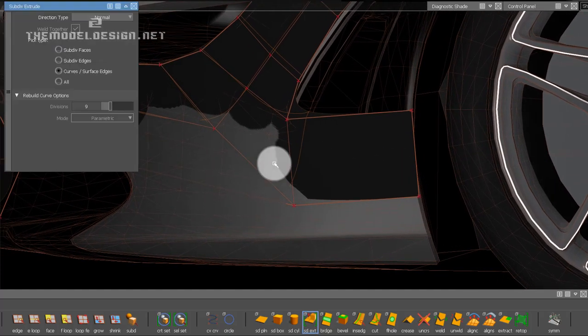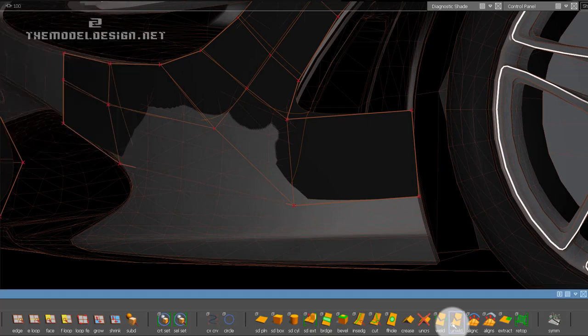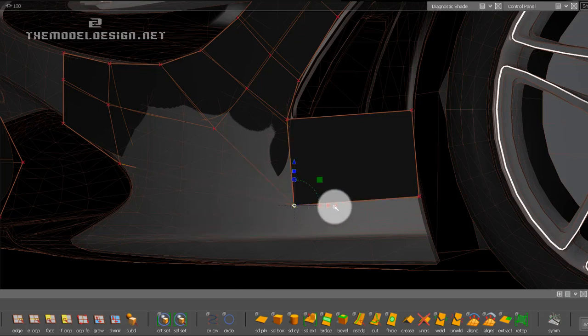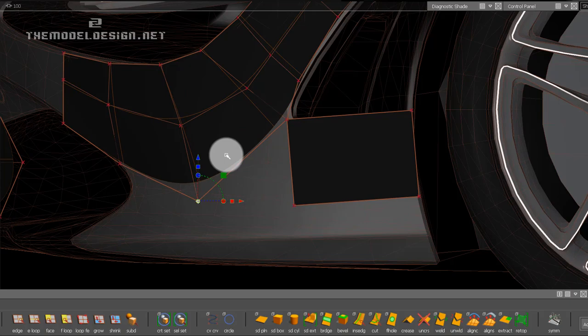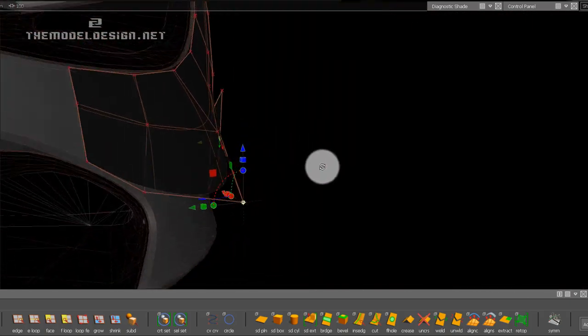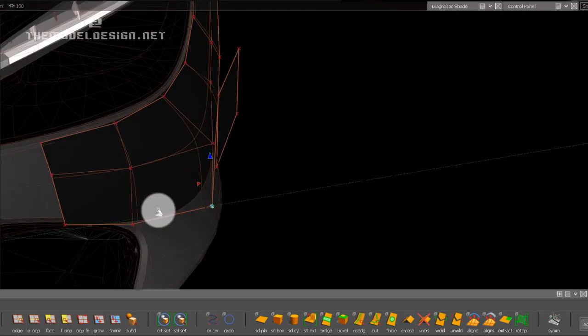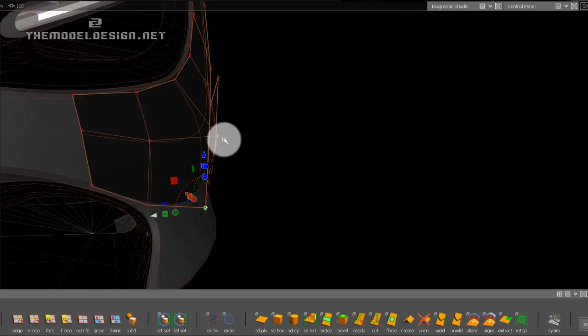We can temporarily unweld the geometry and move the CVs of one patch to the location we want. We are going to be building a gap between the patches, and afterwards we are going to create an additional patch in the gap. The unwelding tool is actually very cool because you can basically detach any patches you want anytime you need.